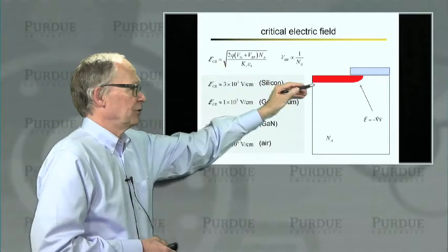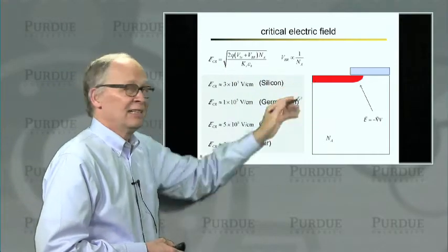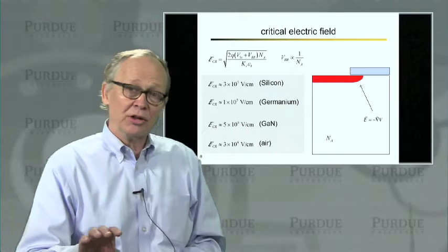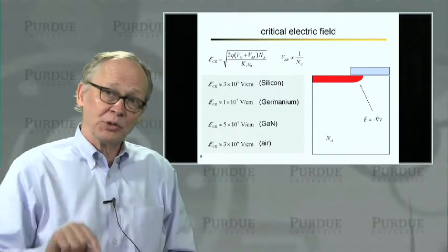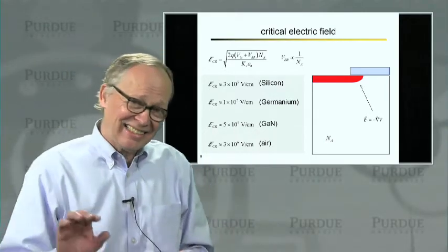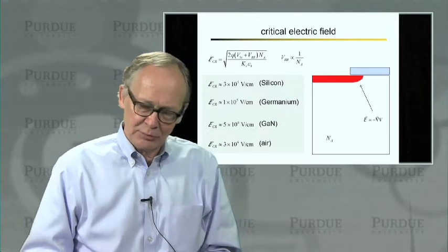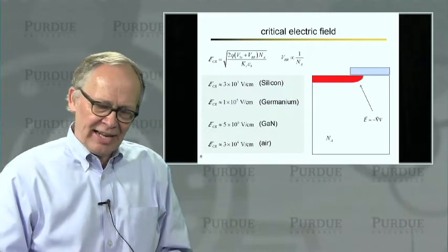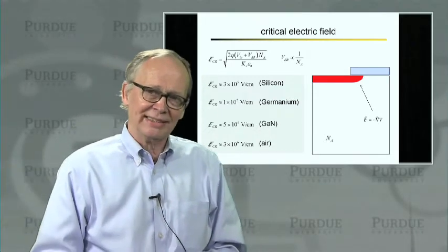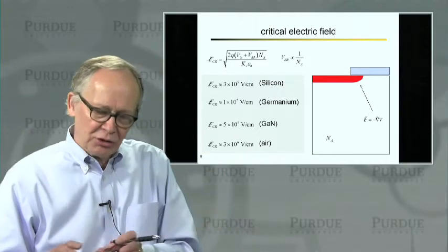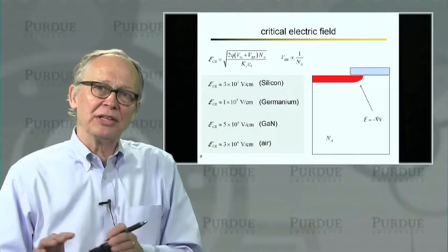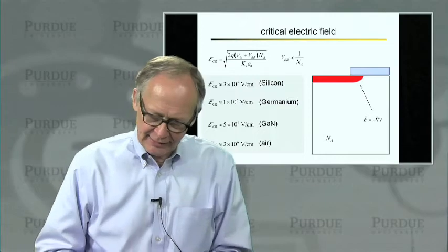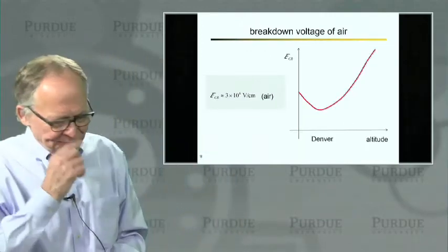This gives me the electric field out here in the planar part. But the device, the diode, is going to break down near the corner where the electric field is the highest. That takes a two-dimensional analysis, and that's more sophisticated. In fact, a lot of power electronic design is about tailoring these fields and smoothing out these curvatures, trying to get the electric field as low as possible.